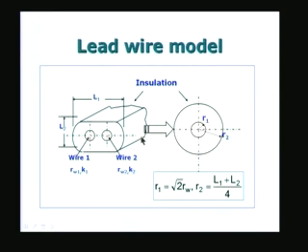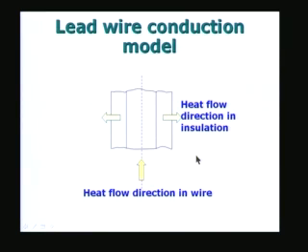And what we did towards the end of the lecture was to show that the two wire actual thermocouple with the sheath surrounding it is replaced by a single wire model consisting of a single wire of radius R1 surrounded by a sheath of outer radius equal to R2, and we explained how to do that one. And in fact, we also explained that the mechanism of heat transfer will be the following.